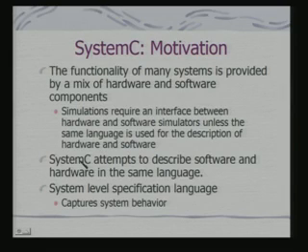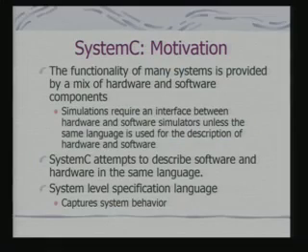If I have identified a subsystem or an object whose functionality I would like to describe, and I describe that functionality using a modeling tool like SystemC, I can describe both software as well as hardware using the same language. That is the basic motivation for developing this tool called SystemC. SystemC in a way is a system level specification language and captures system behavior.